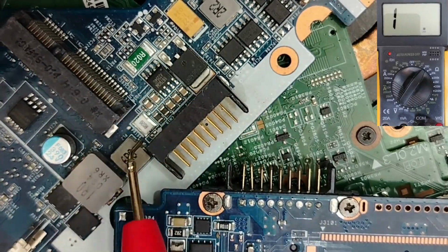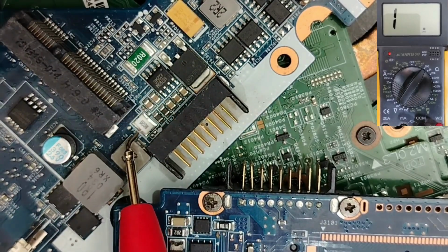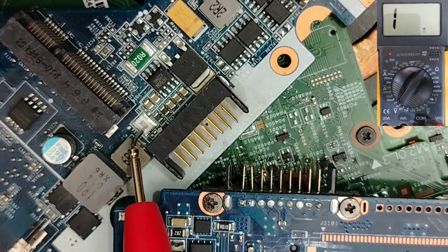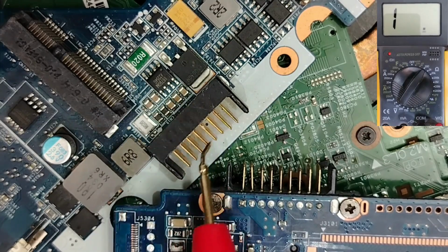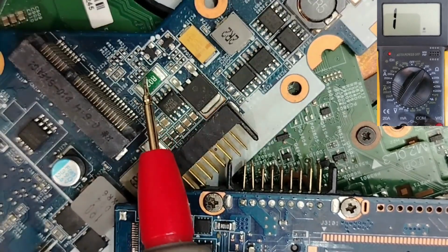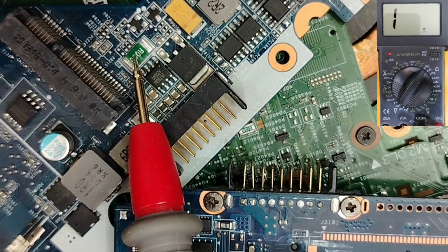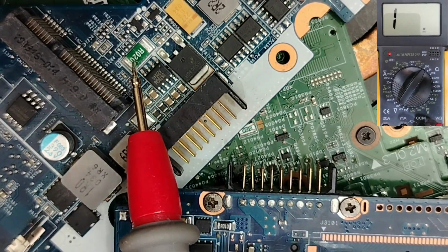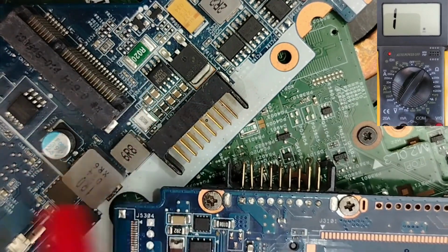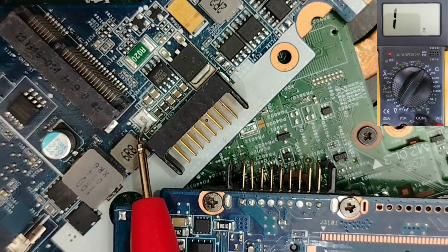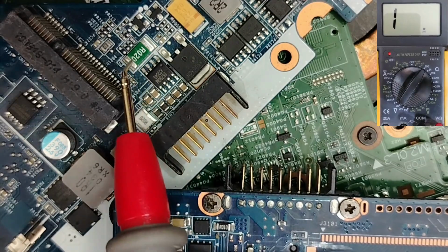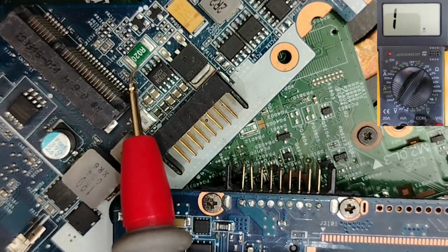Basically, we have another here. Do you see? We have R20. So this one is for the battery connector. So this one measures the current consumed by the battery, and this one here, this is the main, the master one, and this is the slave. This one measures the amount of current consumed by the motherboard including the battery, but this one measures just the battery consumption in terms of current. Okay guys, so please pay attention to the current sense resistor.